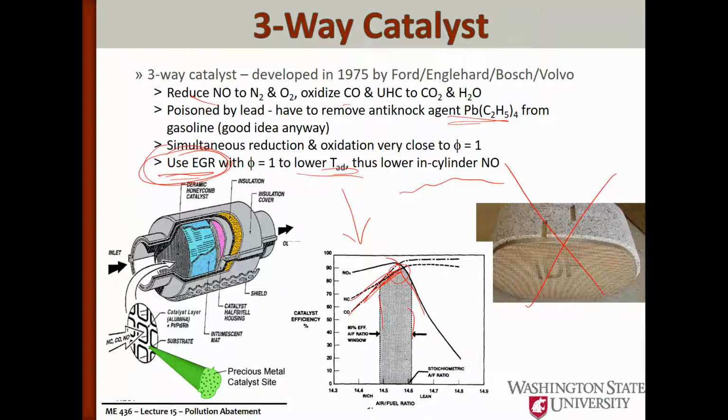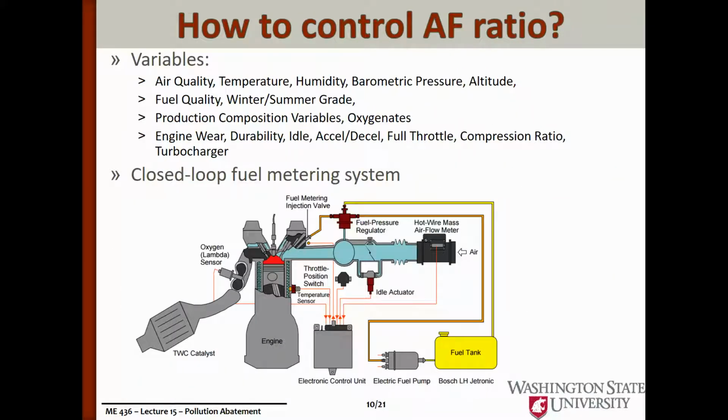How do we ensure that what the catalytic converter sees is in this very small ratio? Now the catalytic converter is downstream in the exhaust system where several cylinder charges have all mixed, so there's some averaging effect by the time it's seen, but we still need to precisely control the air to fuel ratio. And that's done with a control system such as this.